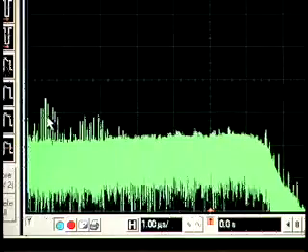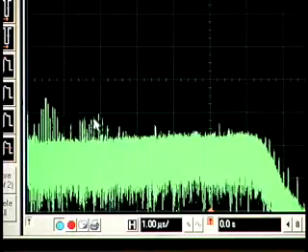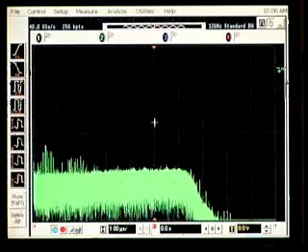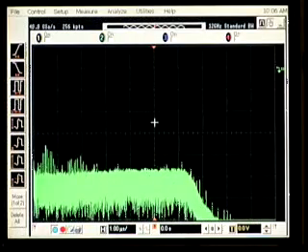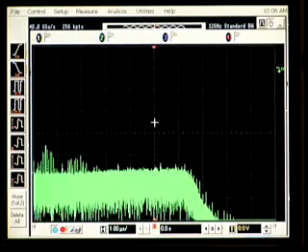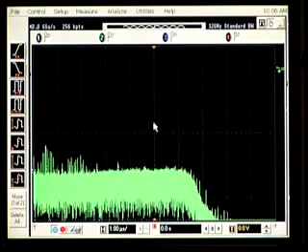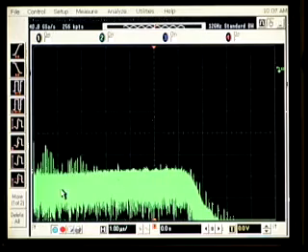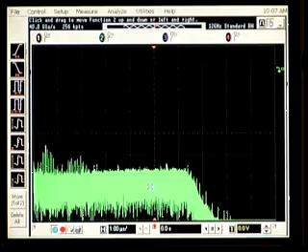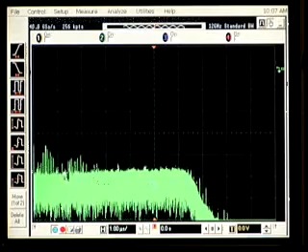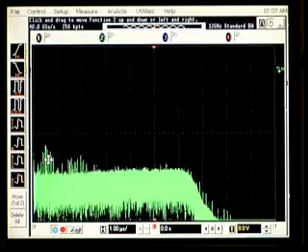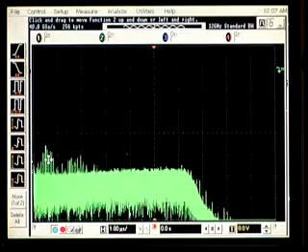The energy in these narrow spikes is quite small because they're so narrow in frequency, so they don't contribute much to the total noise that we saw in our AC RMS noise measurement or in the histogram. That's why the histogram looked very Gaussian. But they are important. This broadband noise, which is uncorrelated, can be removed by averaging. These little spurs here cannot be removed by averaging because they are correlated. They're always at the same frequency.